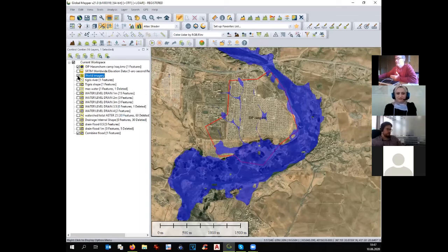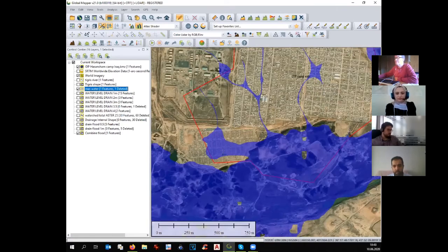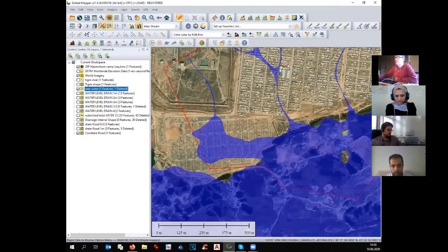You see? Now you will put our point. What is the point? Drain, water source, drainage internal, drainage source, here, max. Okay, we have our point. So you see the flooding analysis: increasing the water level of the river by 3.5 meters, and the internal drain by 1 meter, you will have problem in this area. All this side is going to be flooded.